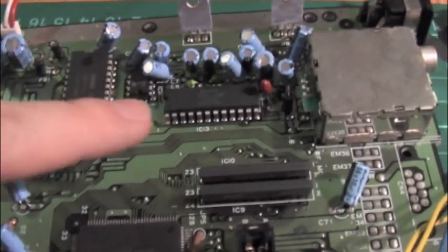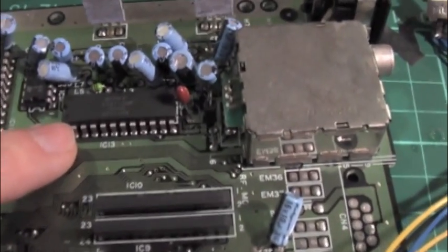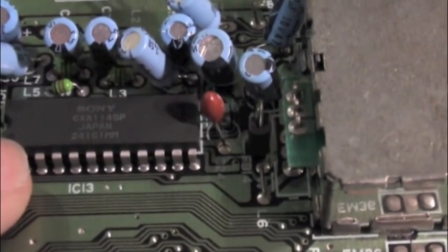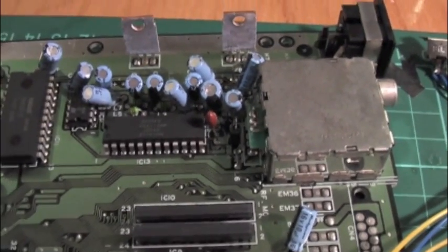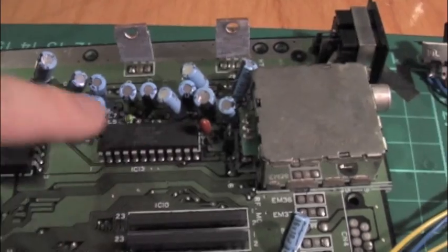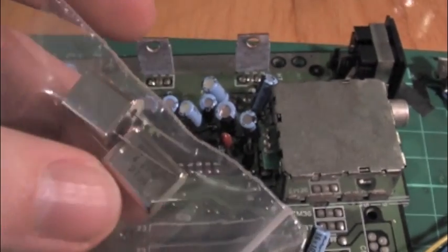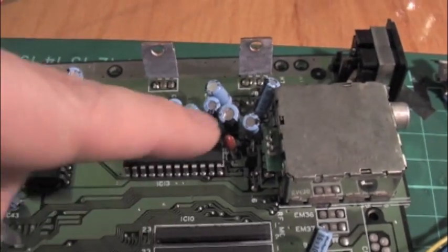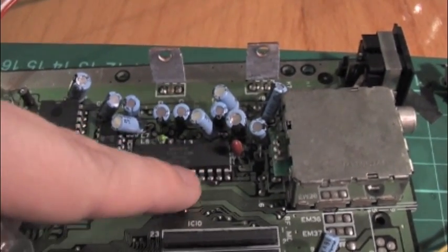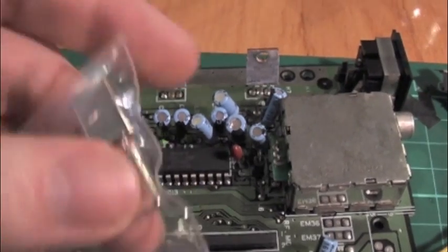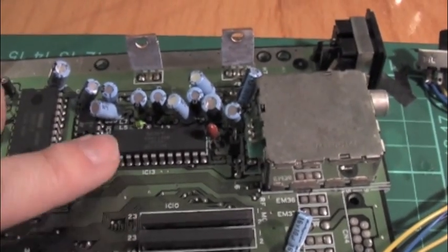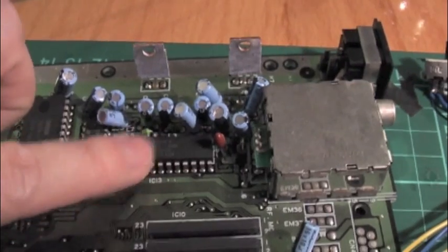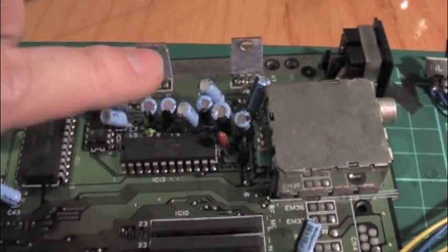Okay, so this is the chip we're interested in, the Sony CXA1145P chip. I'm going to use my fancy new desoldering gun and desolder this chip and solder on a separate timing crystal, so that it only takes the timing for the colour encoding directly from this crystal rather than from the system. That should eliminate the 50-60 Hz problem, and we should get a really nice clean PAL signal.